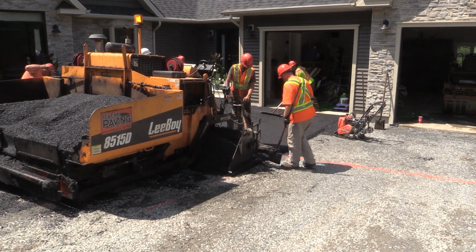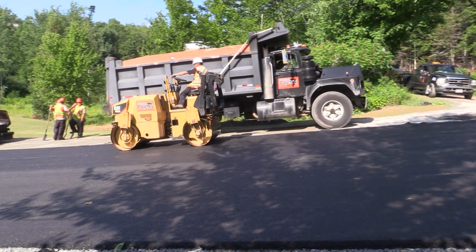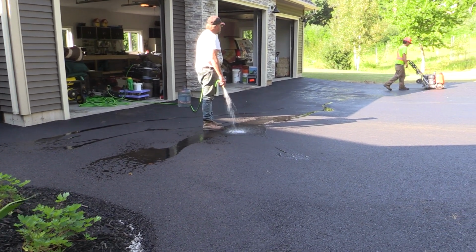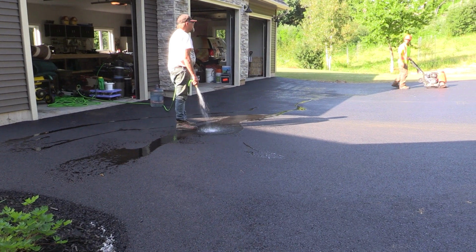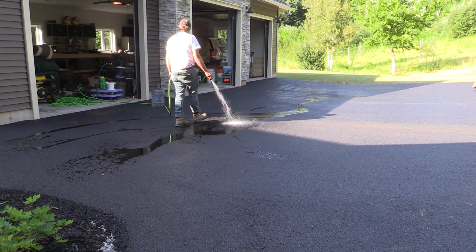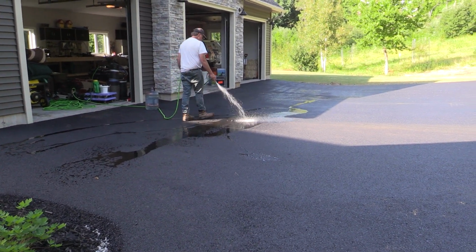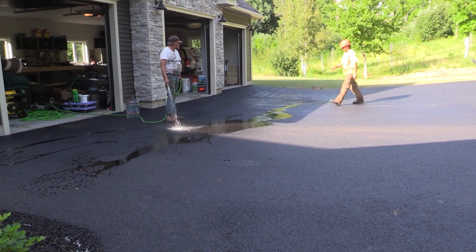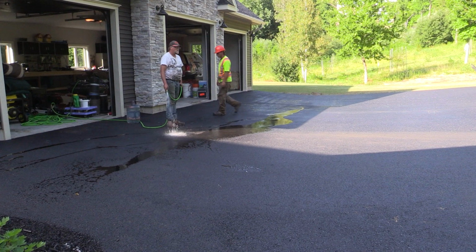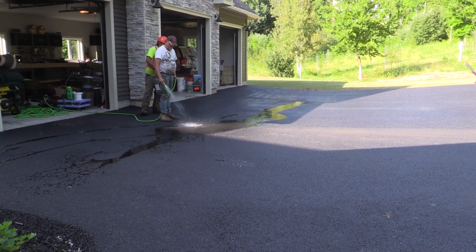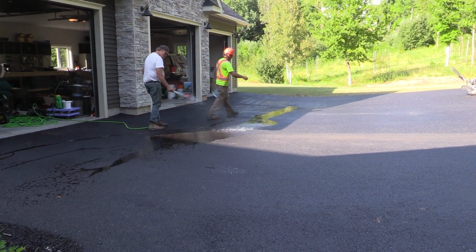Once the asphalt pavement is applied on top of the crushed rock and it is compacted with this machine, the paving crew tests out the driveway's ability to properly drain water away from the house and garage. For this driveway, the paving crews slope the pavement at close to a 3% grade so the water easily makes its way off the side where it will drain into the ground. Knowing how to make these important measurements and calculations makes the difference between a driveway that dries quickly and safely after a rainstorm and one that stays wet and slippery.